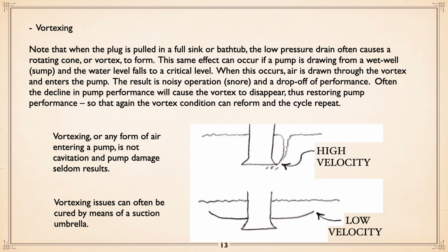And as the pump is sucking, you can get that cone of air coming down to the point where the pump is actually getting that air inside it. When it does, it gets noisy. It's called snore. And you find a distinct drop off in performance. Now, when that performance drops off, very often the drop in flow is enough that the vortex will cease. It'll go back up to a nice level surface, and there's no problem again, but it will reform itself.